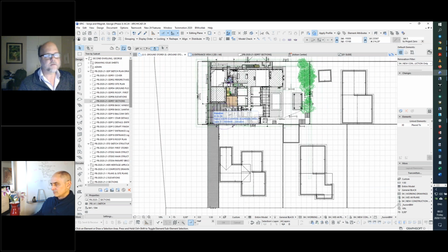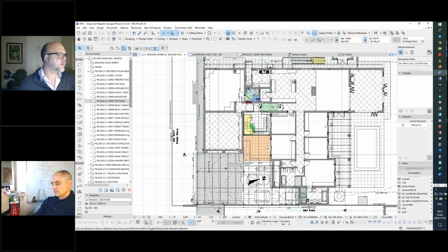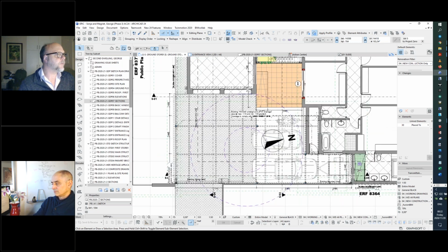It's got a panhandle entrance of 4.2 meters wide, and then you enter into the site, and these blue circles indicate the center of that crane hoist. The largest circle will be the free area which needs to be free for the crane to rotate, and the smaller circle is where the crane bed will be supported with its downwards legs onto the ground. So that's the solid crane position, and then the largest circle is the swing arm free distance that it requires